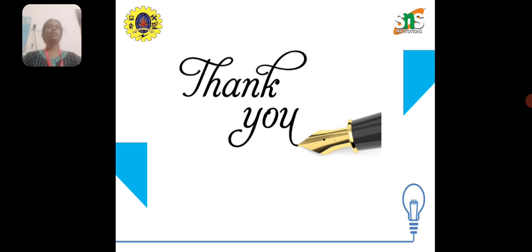And again, considering an input itself is the addition of two signals, and also the scaling property has been applied on that input signal, then the output due to the weighted sum of inputs is another answer. So we have to compare those two equations, and if both are similar, then the system is said to be a linear system. Else, if 1 is not equal to 2, then the system is confirmed as a non-linear system.